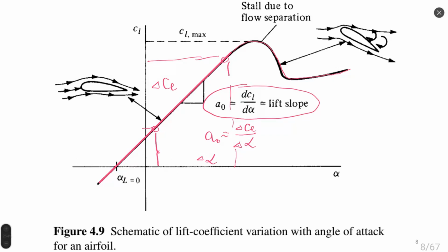So that's simple. And then the curved region corresponds to flow separation. Starting from this point I mark on my screen, flow separation happens, and this region of flow separation, shown on the right part of the screen, is characterized by some volume where we have quite active, intensive recirculation of air.